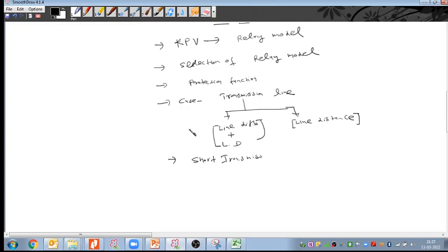So that we discuss both types of relay, the CT requirement for the differential and for the distance also. This distance will be covered for the short transmission line too. We want to take both cases. For the short transmission line, we are taking the RED670 model, because this relay model has both functions. I will come to that relay catalog also, so that we can see that RED670 has both functions.